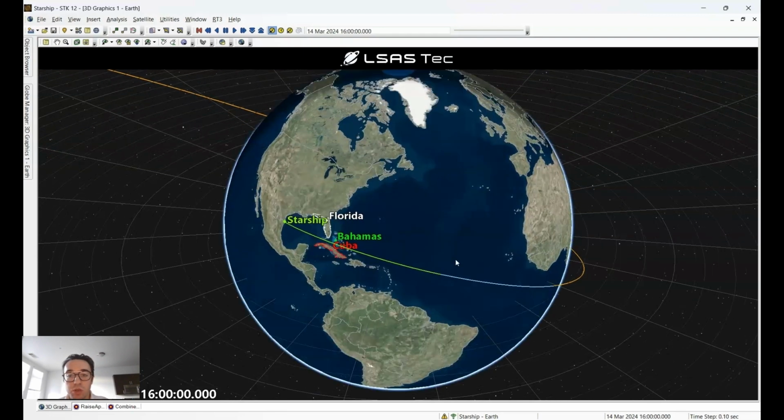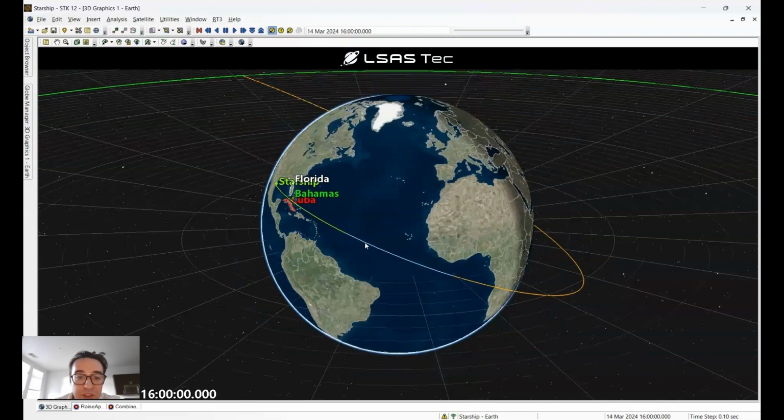So we managed to show these two things, and thanks to these parametric and carpet plot studies, we managed to also see which were the lower and upper bounds for our design variables, both the downrange distance and the azimuth at burnout. So we managed to see which are the optimum bounds for these two design variables that allowed us to set up an optimizer tool run that was more efficient to start from because we had more defined bounds.